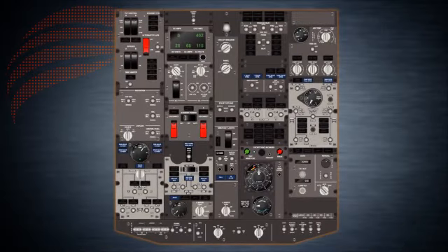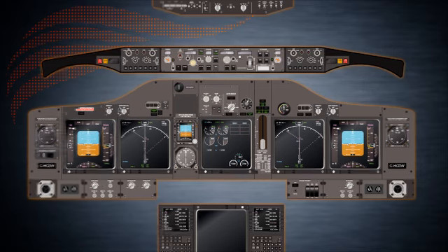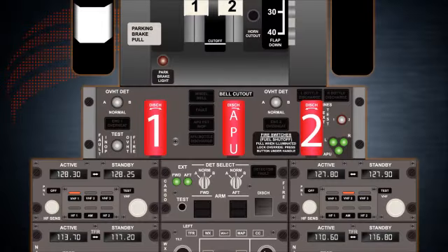Blue lights are for information and do not require immediate flight crew action. They inform the flight crew of electrical power availability, valve position, equipment status, and flight attendant or ground communications. Some blue system lights also indicate valve or component transit by illuminating bright, and bright illumination may also indicate a disagreement between switch and valve position. Green lights on the 737 flight deck indicate validity, such as landing gear and leading edge device extension lights, the speed brake armed light, valid squib tests, window heat on lights, and pressurization system modes.